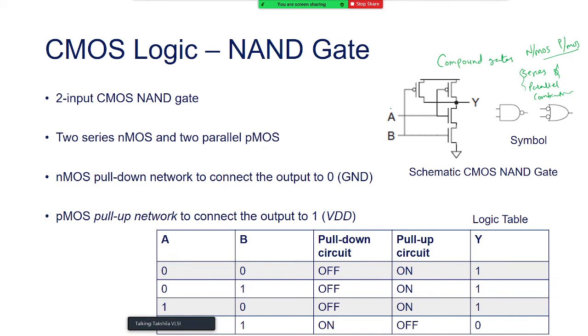For example, I wanted to create the 2-input CMOS NAND logic. So I know that the NMOS got in series here, and the PMOS, just because the NMOS got in series, I got the PMOS in parallel. This network was the pull-up network, this network was the pull-down network. And again, I have 2 inputs, so 2 to the power 2, that is 4 combinations of input were possible. From 00 to 01, 10 and 11, I just analyzed how this circuit works.